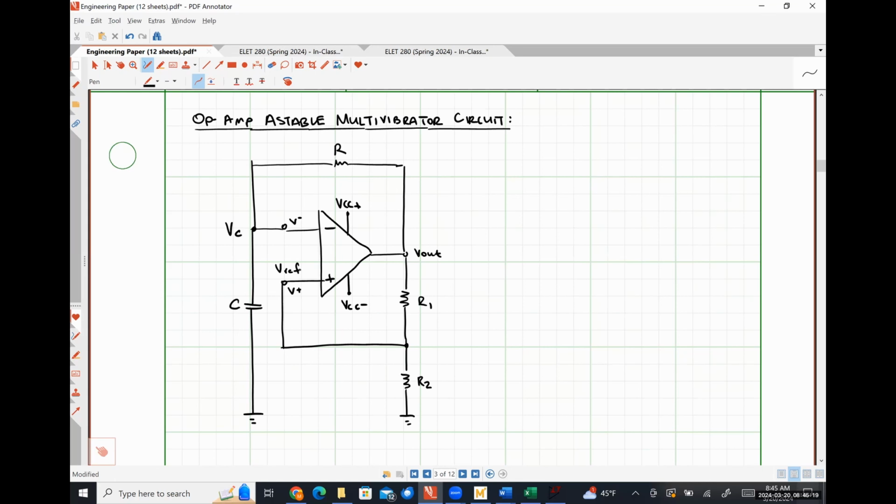And so our reference voltage is just a scaled down version of that output voltage because it's just the output of a simple voltage divider, effectively, right? This node right here is also VREF. And so we can see that it's going to be approximately equal to whatever Vout is times R2 over R1 plus R2. Just simple voltage division there, nothing remotely fancy. Okay. So I'm going to make a couple of plots here.